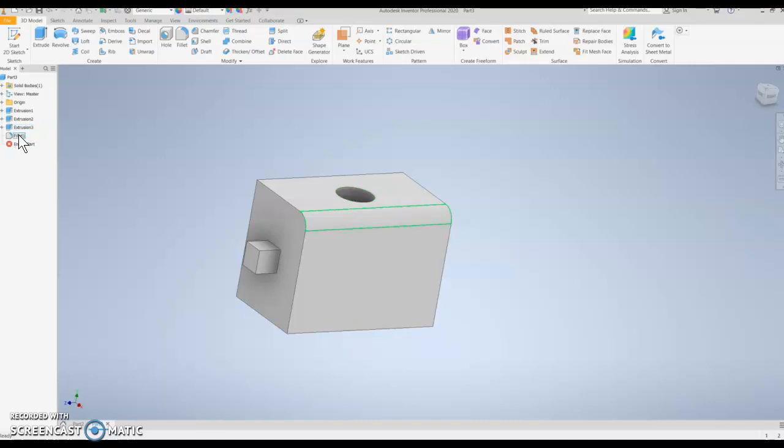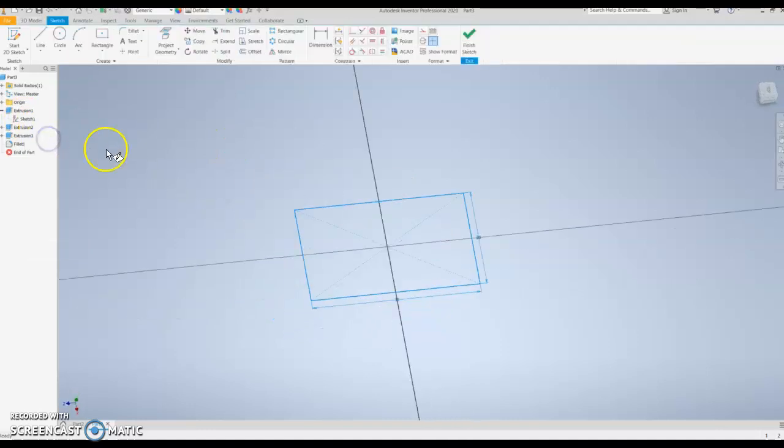You can change and adjust these. So if we look at our original object that we were working on here, if we click the little plus sign beside it, it shows us our original sketch if we want to look at it, and then it shows us the feature that we created through the extrusion. If you want to change or edit either of those, we simply right-click on it and say Edit Sketch.